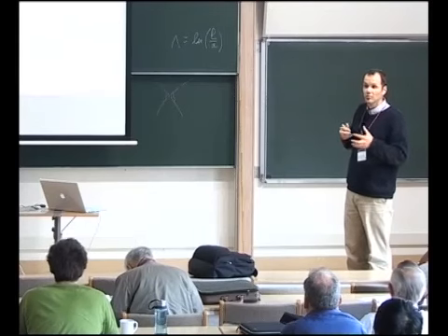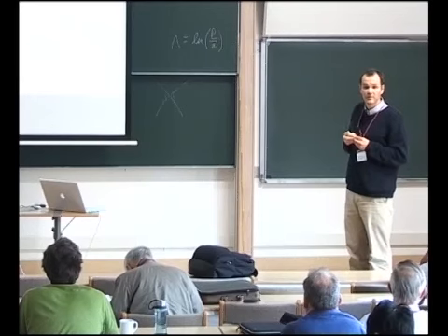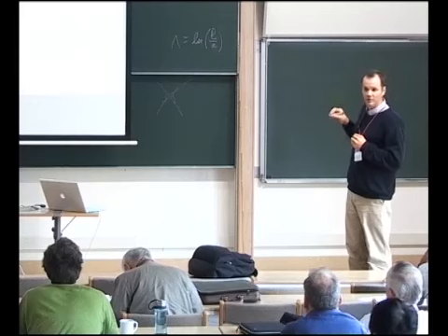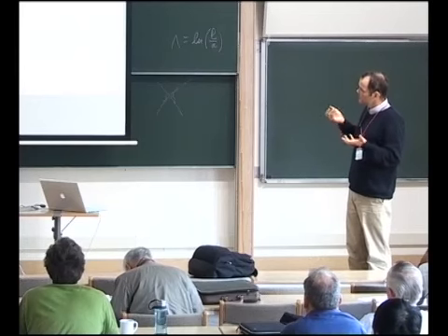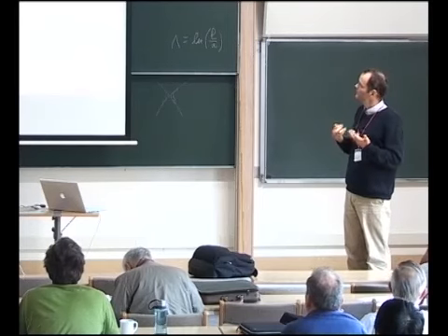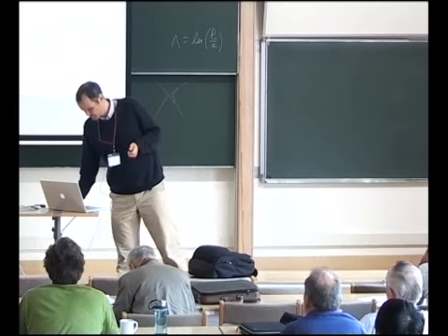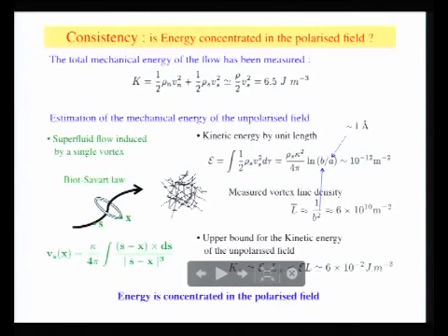On the other hand, we want to check whether a vortex line in this unpolarized field is transported by the flow. Since we assume that the flow is incompressible, when we stretch and pull a fluid element, the total vortex line is conserved. So we have some ingredients to justify that the unpolarized field behaves as a passive field, to some extent, of course.